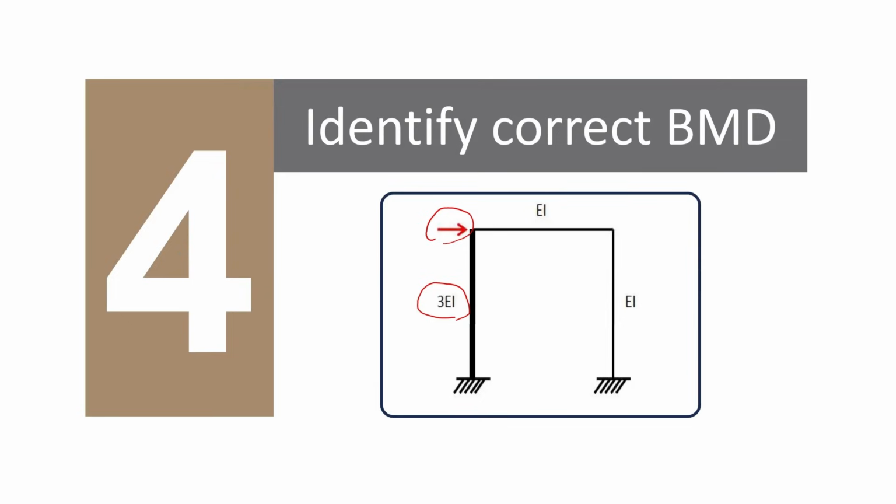And this structure is an indeterminate structure. Indeterminate structure means that this cannot be solved using ordinary equilibrium equations. The reason is that this has 3 reactions at each support, so 6 reactions altogether. Equilibrium equations are 3, so we cannot solve it using equilibrium equations.